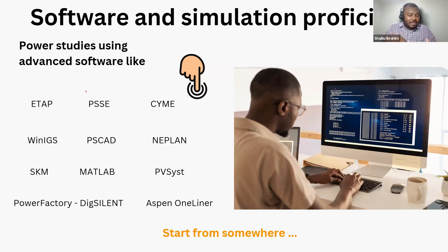If the cable is going to be installed underground, what is the soil moisture of the ground? What will be the soil temperature there? What will be the thermal resistivity of the soil? How easily does the soil allow heat to dissipate? All of this has to be done in software because it's really difficult to solve with hand calculations. So we in the industry have built software that is very good, very advanced, and can do almost all scenarios. Even if the cable is going to go under the sea, we can study that and simulate that to know the condition of the cable to select or the cable to buy.